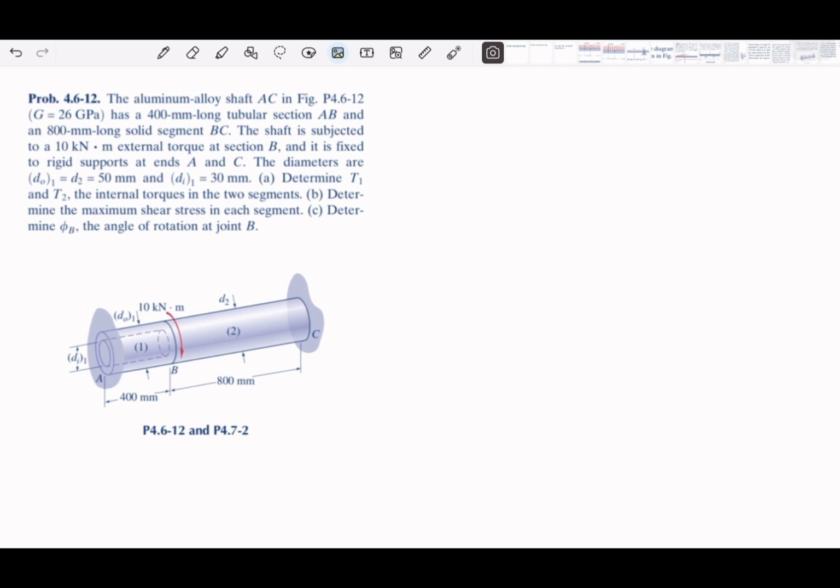Suppose you have something like this attached to the wall. You can focus more on the geometry or shape, and figure out how the deformation will be. You can add the compatibility equations, which is that the total of the twist angle or rotations will be 0, unless there is some information given in the problems.